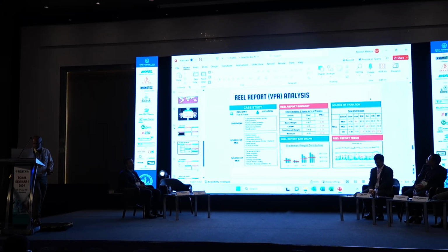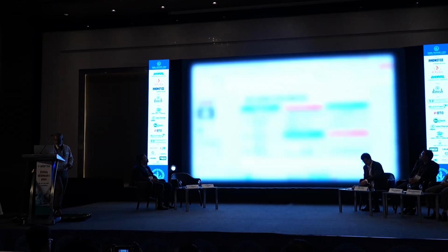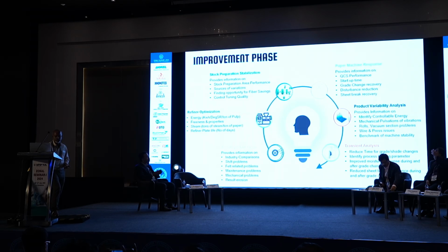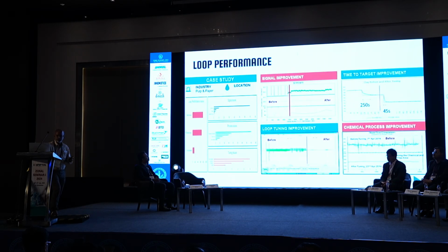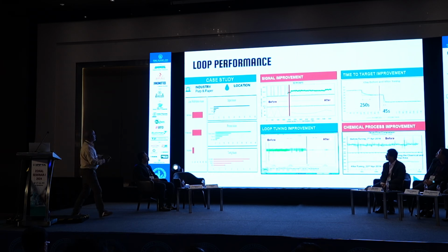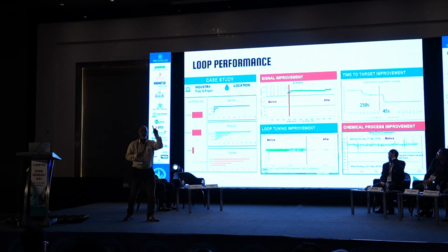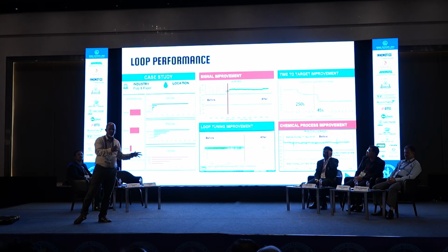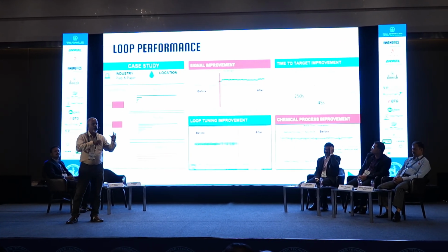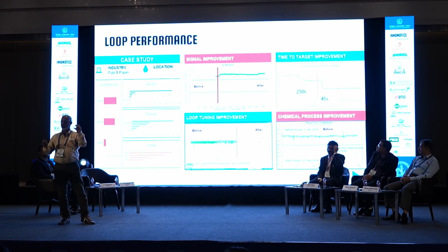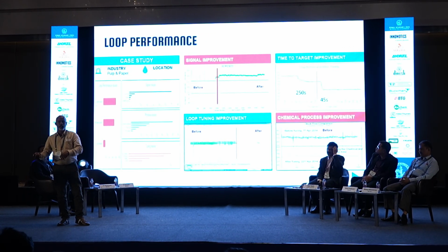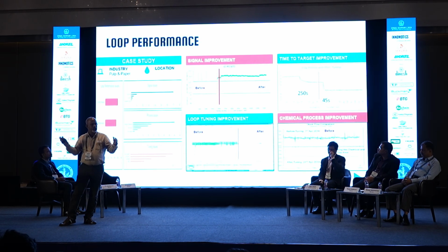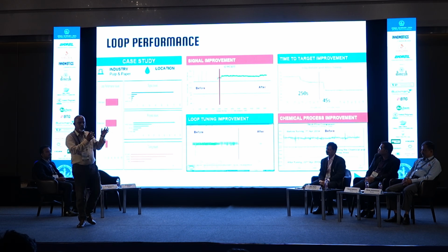Once I understand this, we have to go for the refiner optimization and then stock stabilization. Again, I want to quickly go through this. For example, we have n number of control loops. One control loop has pipeline, pumps, tanks, and transmitters: how the transmitters are set, where they are installed, where the valves and pumps are, and what the equipment is doing. All this information is in one control loop. We analyze all your 100 or 300 loops in your stock preparation.